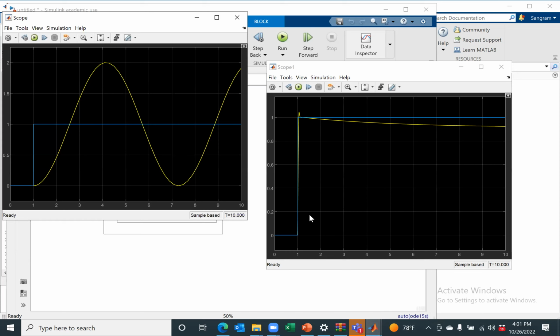So this is the basic application of PID, wherein you have a system that is initially not controlled, but using some type of PID gain, that system can get controlled. Now there is a lot of math that goes inside, but the crux is that at the end of the day, it is going to change the eigenvalues or the poles of this system.